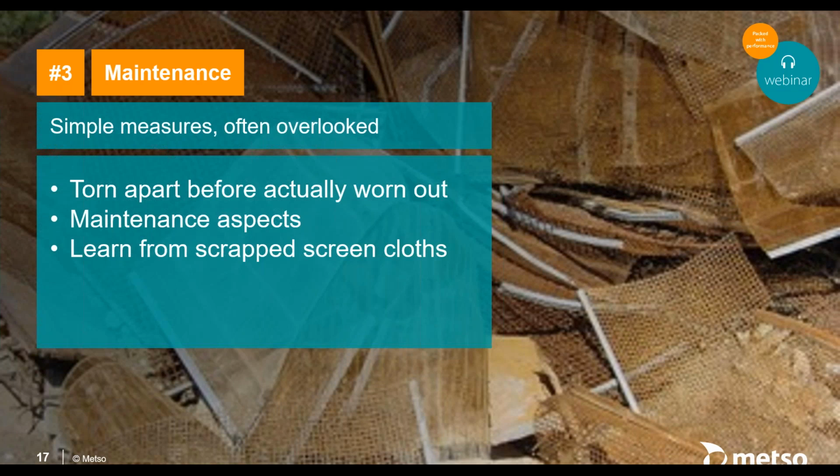In quite a few cases, the screen cloths are actually torn apart or destroyed or broken before they're worn out. This originates in various maintenance aspects. But the most common thing is that you can learn a lot from scrapped screen cloth: how they broke, where they broke, and what you can read out of that.